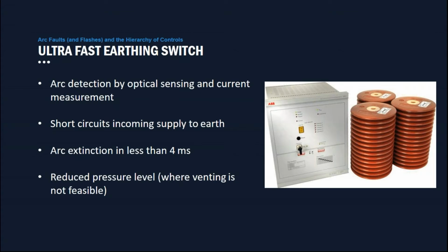But they tend to respond in something like 4 milliseconds, so very, very quick, and they change what arguably would have been a phase-to-phase fault through air. By shorting those phases to ground, we then have a sustained phase-to-earth fault, but of course that is much more manageable than the plasma that we're getting from an arcing fault.